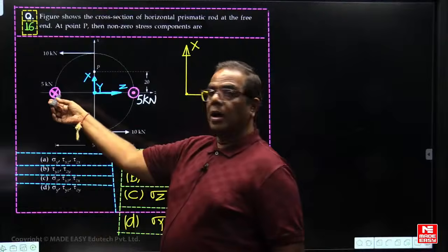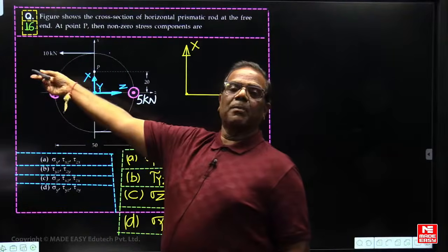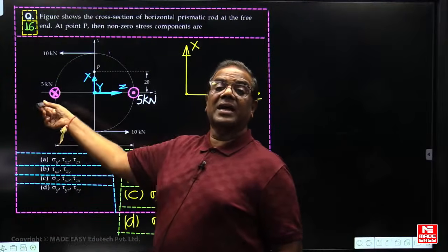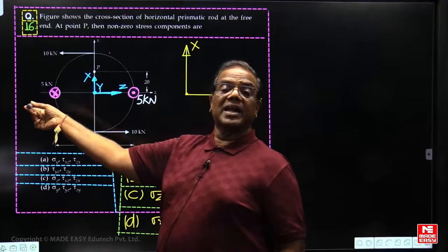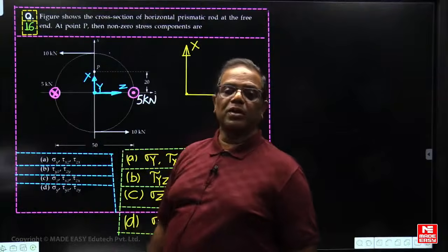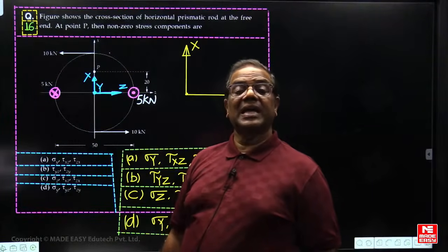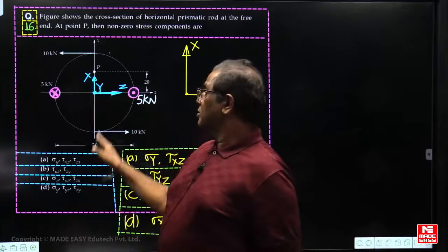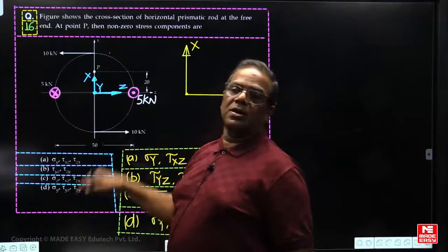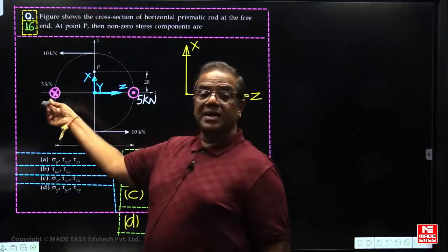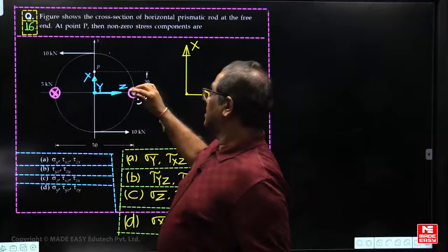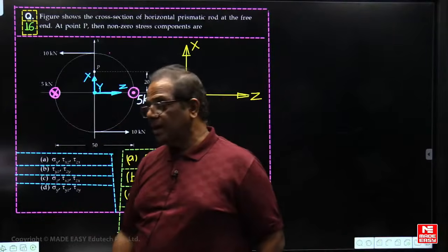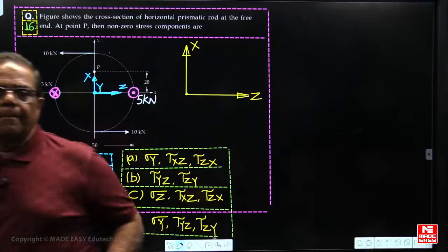So here, on VCA, which load is applied? ETSL is applied. On HCA, this is an eccentric axial compressive load. Cross means inward. So this is loaded by ETSL and EAL. This is horizontal ETSL. So these two will form a twisting couple in anti-clockwise direction. And this eccentric axial compressive load inward, this eccentric axial compressive load outward. Now these two will form a bending couple.